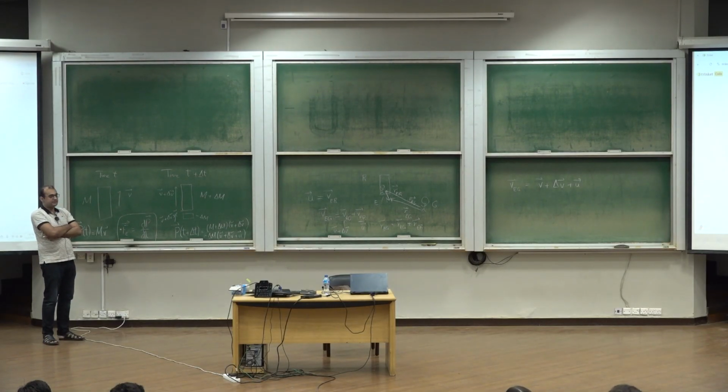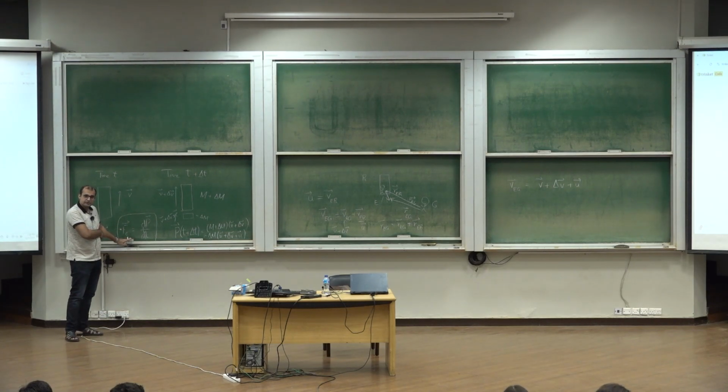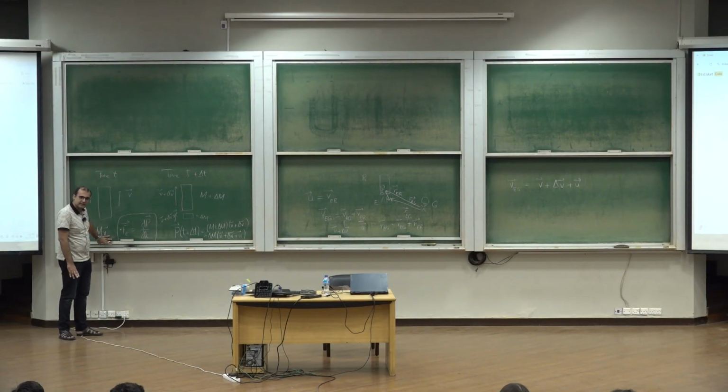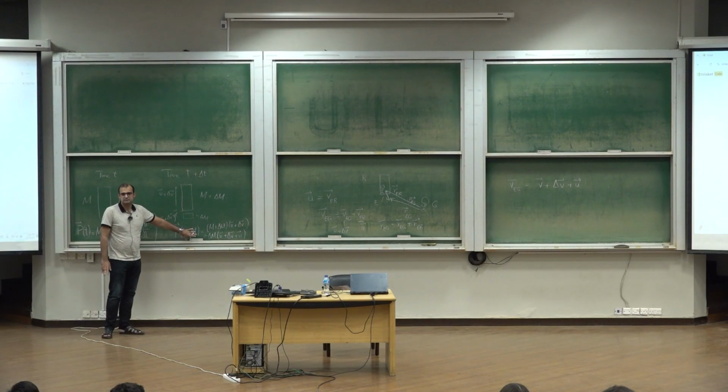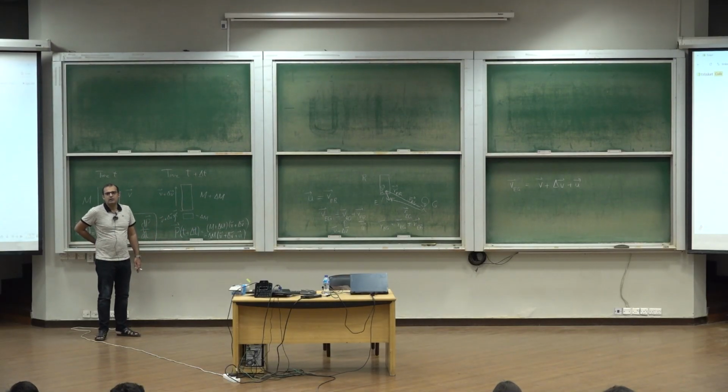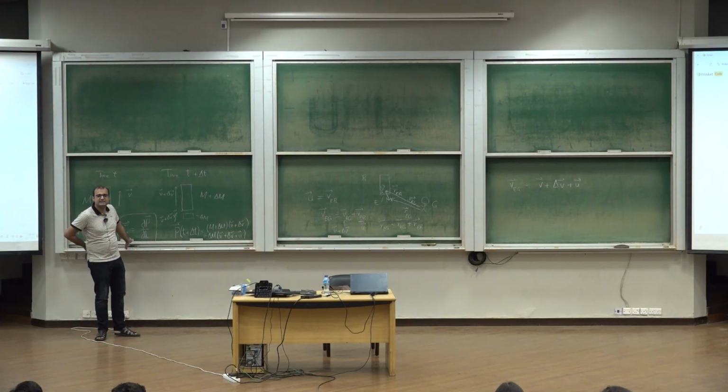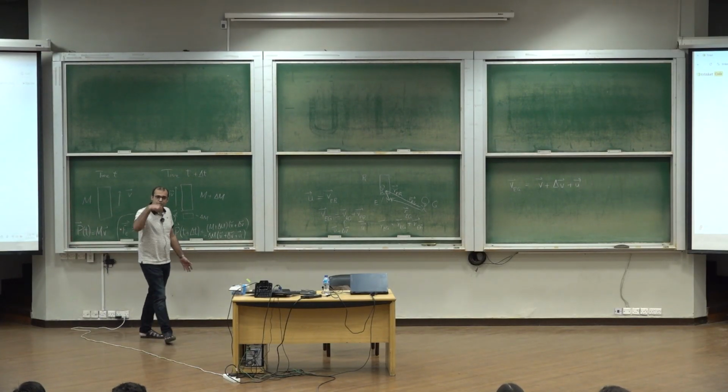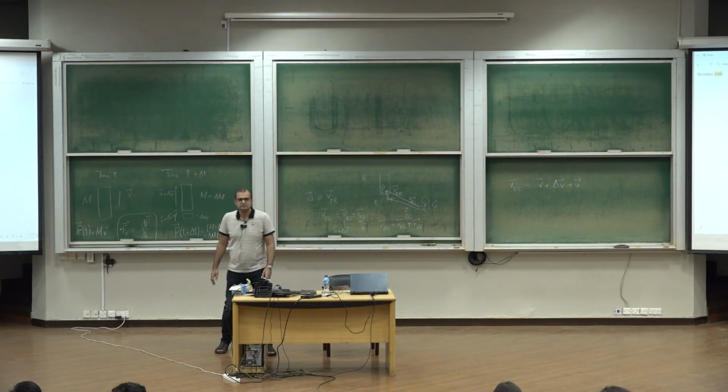Yeah, sure, but to apply this, you have to make sure you consider the momentum of the whole system. नहीं, वो काउंट कर सकते हो, वो भी कर सकते हो, या उनको इंक्लूड करते कोई फर्क नहीं आता, आपका आंसर सेम ही आएगा, क्योंकि what matters over here is the change in the momentum. जितना जो बाकी गैसेस है, जितना उनका मोमेंटम इधर होगा, उतना ही उधर होगा. हाँ, तो मोमेंटम चेंज हो रहा है ना, बट उन जो एग्जॉस्ट गैसेस टी से पहले निकल चुकी थी उनकी वजह से नहीं चेंज होगा. जो एग्जॉस्ट गैसेस ड्यूरिंग डेल्टा टी निकली उनकी वजह से चेंज होगा.